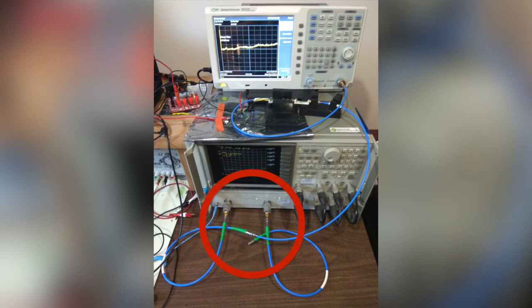Then you want to hook it up to one of the ports on your VNA and measure a reflection coefficient at the end of that cable. That cable is eventually going to end up at the output of your DUT. But for now, the purpose of this is just to de-embed the reflection coefficient of the entire system downstream of that point. So an additional consideration for step 4 is VNA power as seen by the preamplifier.